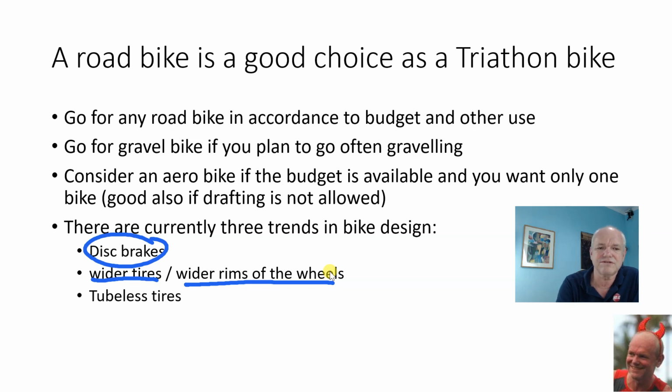And then also very often they use tubeless tires. That is another trend now. So you don't have the inner tube anymore. And with this you can go on quite low pressure. Now we know that low pressure, not high pressure like before, like 8, 9, even 10 bar, so sometimes now they are using only 4, 5 bar, you are fast. You are even faster than with a high pressure bike.